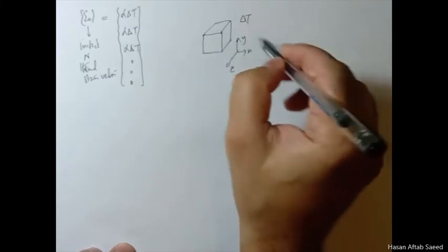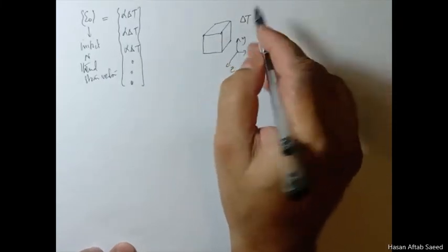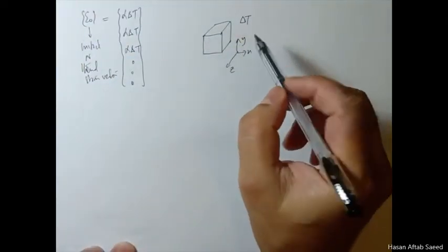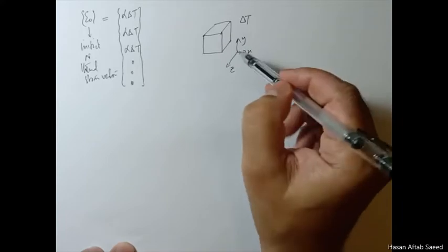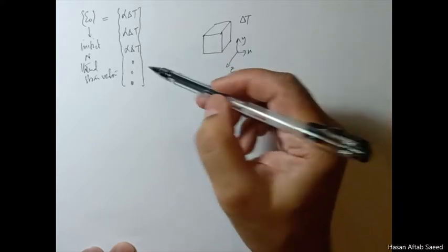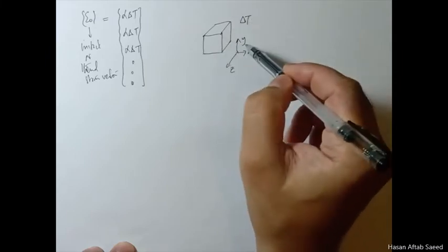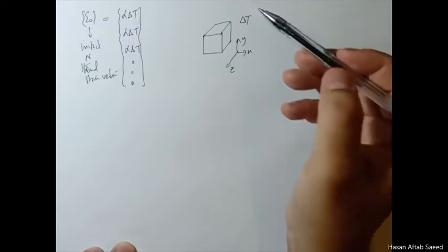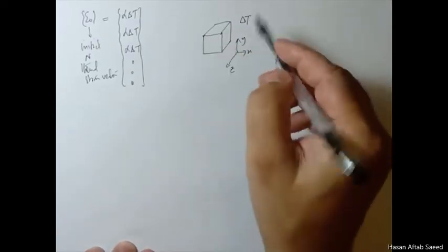So there will be thermal strains, which are associated with no stress here, because it's just thermal strain, not mechanical strain. So you have this strain in 3 directions, x, y, and z. But as far as the shear components are concerned, they have nothing to do with thermal strain, because shears would imply changes of angle, which don't take place with the temperature change alone.